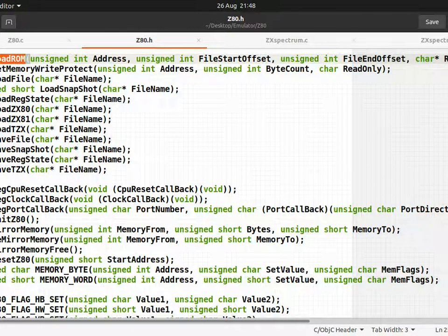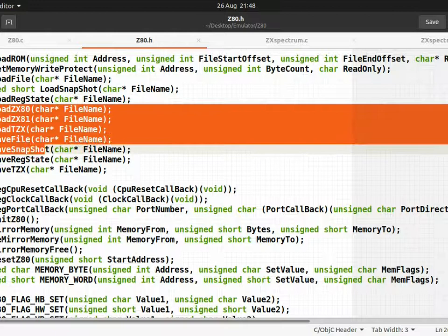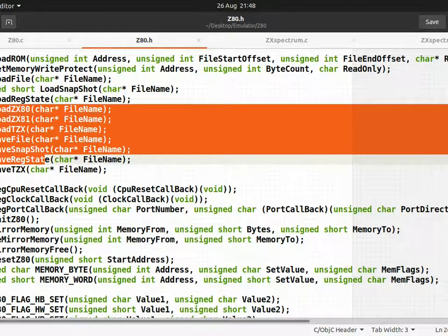So I've got some specific stuff in here as well for loading and saving particular files into memory, because the memory itself I've put in the Z80 CPU code as well. The memory is just an array of bytes, so it doesn't matter if I just sling it in the Z80 stuff and really make this into almost a microcontroller itself. Then I do all the memory management in here, because every computer needs memory, and I just supply the full 64K, which is the maximum that the Z80 can actually address.